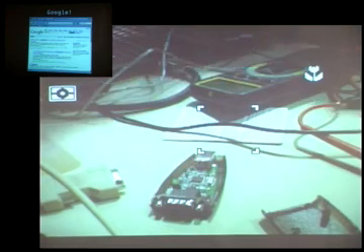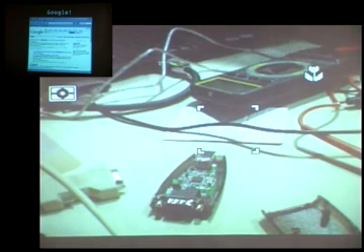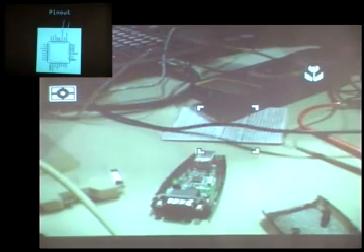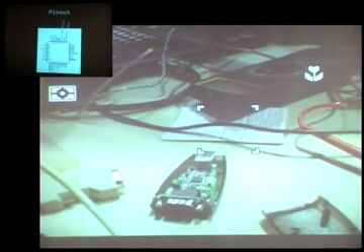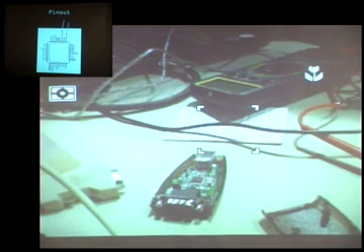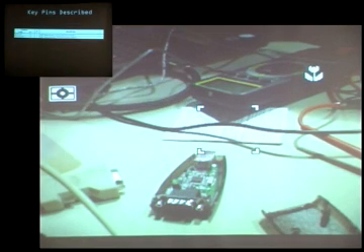You're great, right? You pull up a data sheet, you read it. Life is good. This is a pinout from the data sheet itself, and so you look at these pins here, that's a serial in, that's a serial pin. So now I know what pins I want to go ahead and solder onto to tap them off and go to my embedded controller. We've got to do a little more work though.